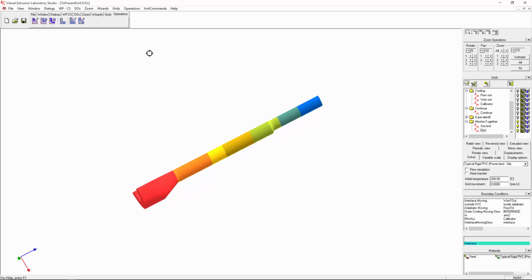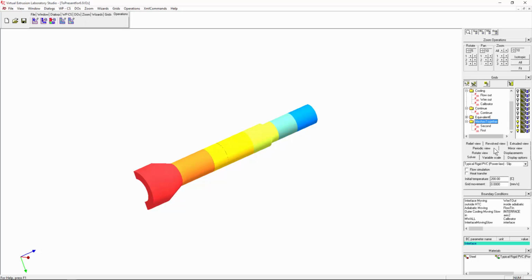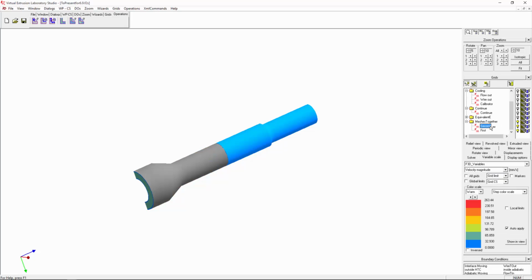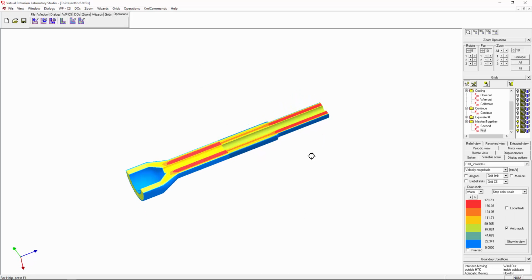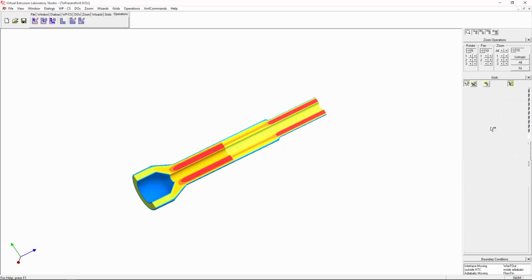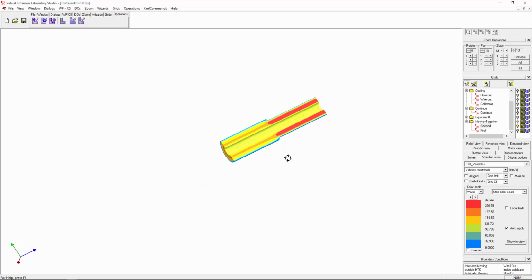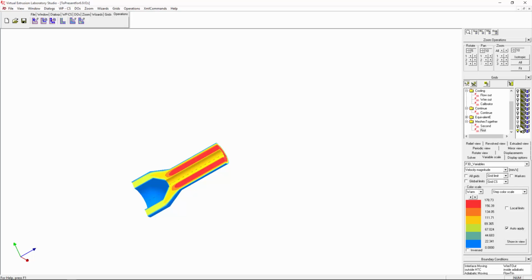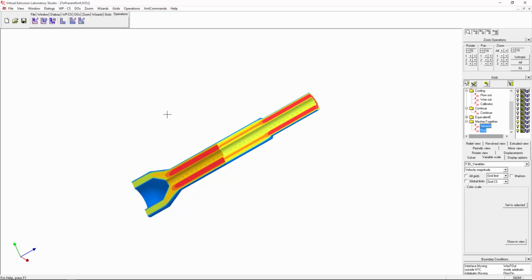Okay, so what would be the reason? The reason would be that I can solve these two meshes either together, that I multi-select them, or I can solve them one by one, right? So if I just want to solve the second one, no problem. I just start the solution, and I put here input boundary condition. That's it. If I want to solve the first one, no problem, I can solve it as well, but I need to know the back pressure from the previous one, which I can get very easily. Or I can just multi-select them and start them together.